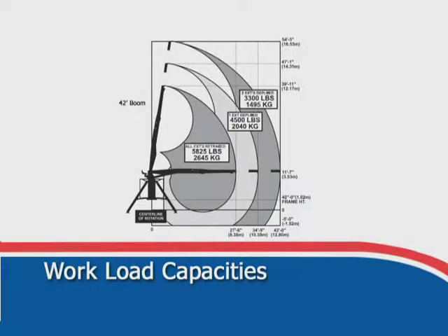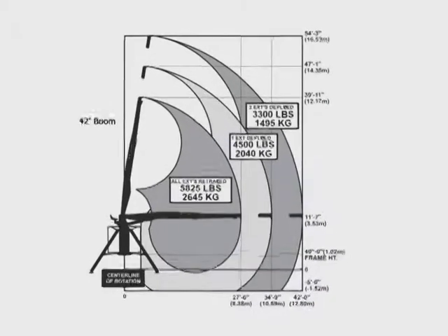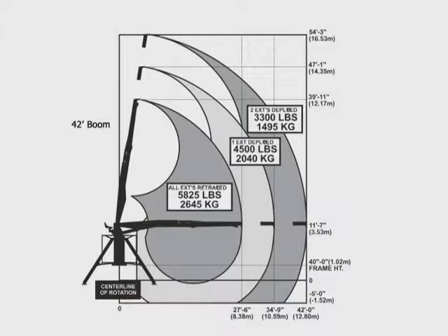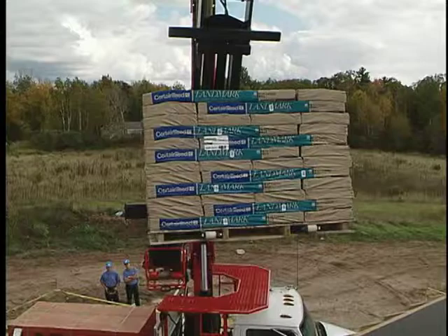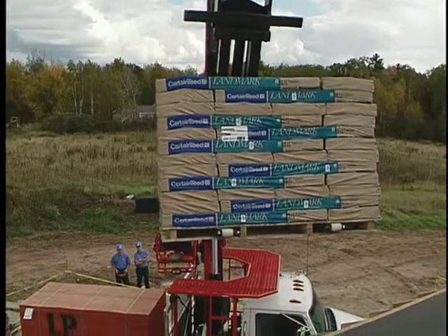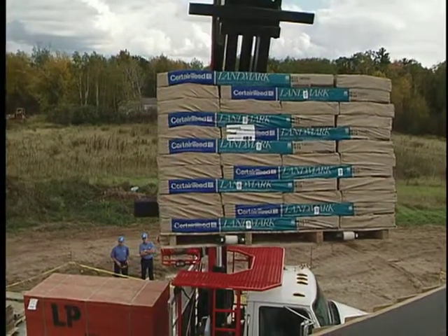Note that there is a relationship between crane extensions and load carrying capacity. This diagram explains. The further the load extends from the center line of the crane structure, the less weight, measured in thousands of pounds, the crane is designed to carry. The extension and strength of these cranes should allow you to reach openings several floors high.